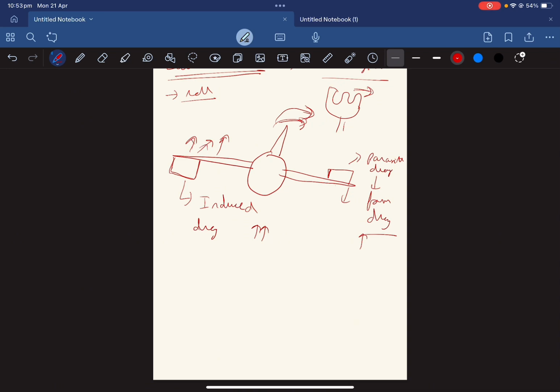So you're rolling to the right, but your nose is moving to the left. Are you getting it? So this is something you don't want, right? You're rolling to the right, but your nose is going to the left just because of this drag. So this is called secondary effect of roll, or also known as adverse aileron yaw.